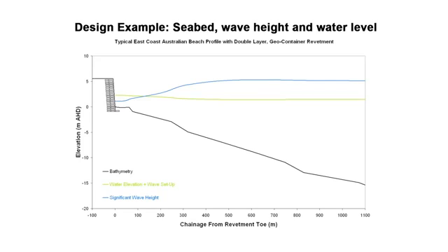So we have a little bit of wave setup in here which brings our water level up quite a bit higher than what we were out in the deep ocean. So that's how we get our wave height at the structure. That's a mid-level way of doing it. There's even more sophisticated ways, but that's a 1D numerical model.